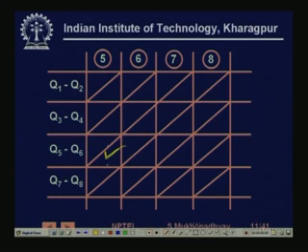So, this is exactly what we are doing. We are first exciting one coil of one phase only, then we are exciting this and this, so that the rotor moves half a step, then we are switching off this excitation so that the rotor gets completely aligned with this one.